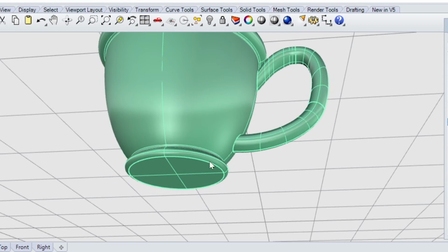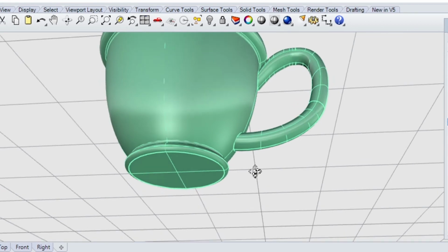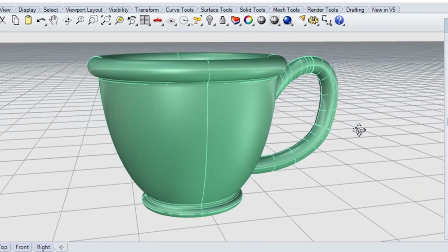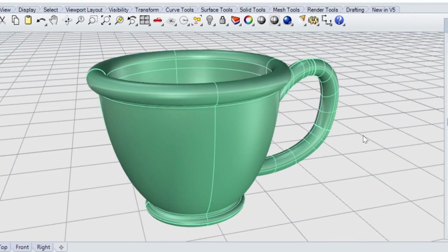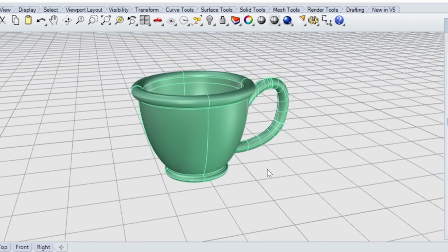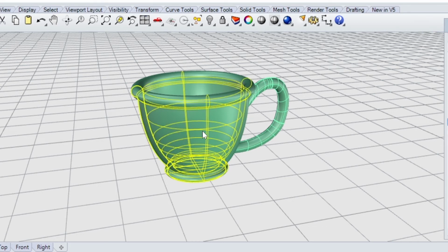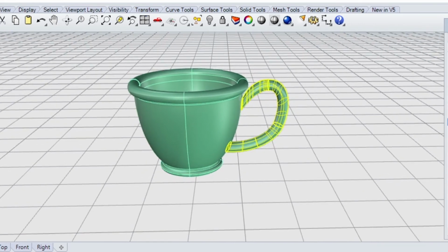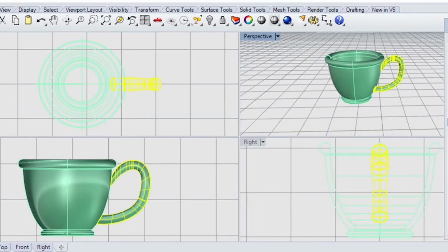Is it located flat and sturdy on the build plate? Definitely. It will definitely also print with some support here. I don't know if we can reorient it so that it wouldn't, but we've checked the first 3 boxes now. Last but not least, what happens if we select this? Odd, it doesn't select the handle, and vice versa. That's because I have tricked you.